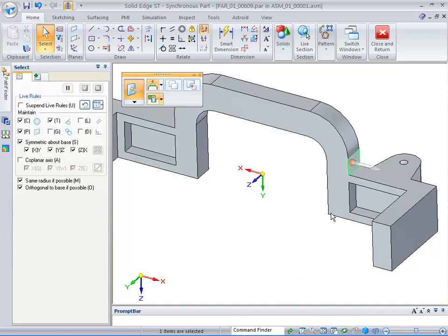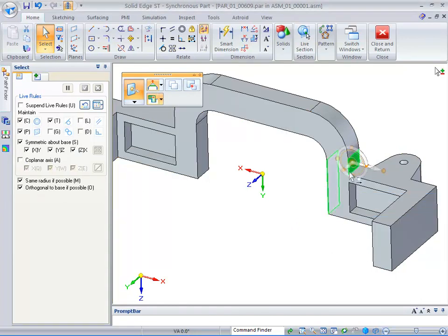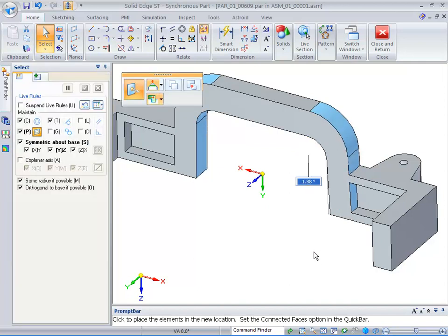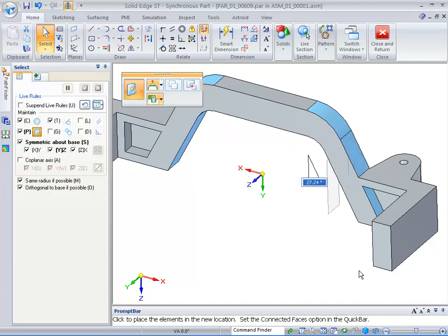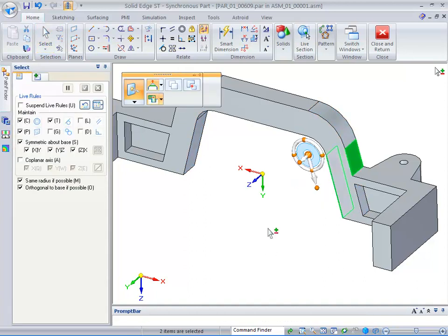At that point, you can pick this face and pick the inside edge here. Move your steering wheel to find the center of that arc. I like to point the arrow down because that's the direction it's going to be measured from when I go to rotate this. And you can show that that is going to maintain its planar alignment. Stay lined up. You can create that angle.